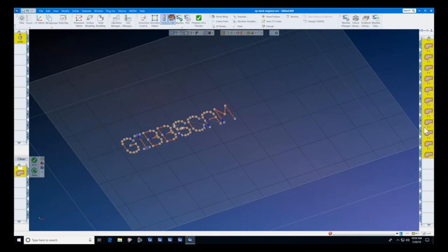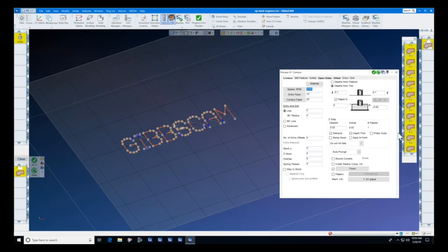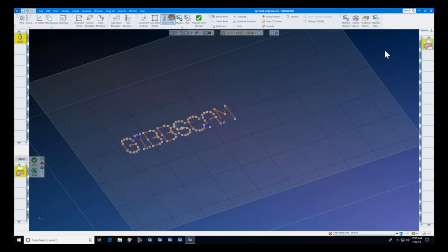Number one, we compressed all 11 of those ops into one op, which means that we can see more items here. But as you can see, the numbering scheme stays just like it should. You can see that ops 1 through 11, if you wave your mouse over it, are all compacted right here in this one op. And when we double click on it, they all come back open. We make a change, we press redo, and the op closes again. And you can see the next available op tile is op number 12. So op stacking is always available to you, and you simply click this button.